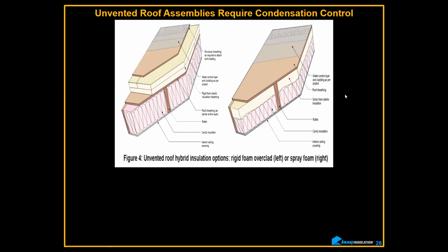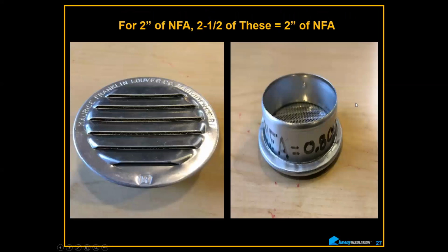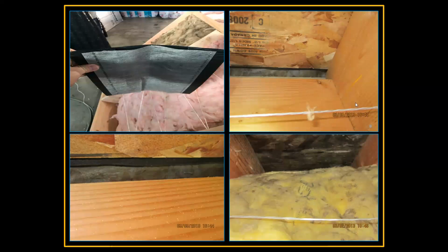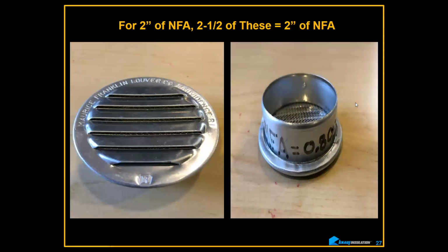The only difference is how much insulation you need in the cavity and how much you need to control condensation. Okay, and then just a couple more. Kraft paper for climate zones 2 and 3. Twenty-five years ago when I was training under an inspector, it's like, oh, you put the paper on the warm in winter side.